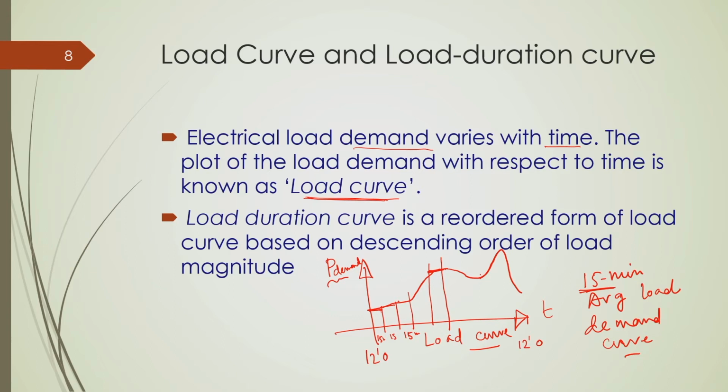So, the load demand curve is essentially the characteristic of power demand with respect to time, and there are different types of load curves, which I will be discussing right now.